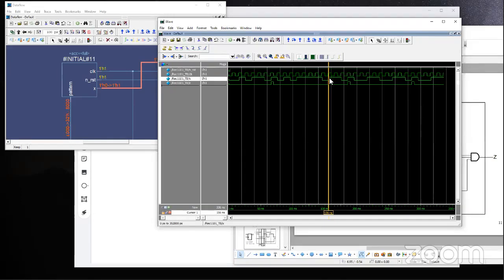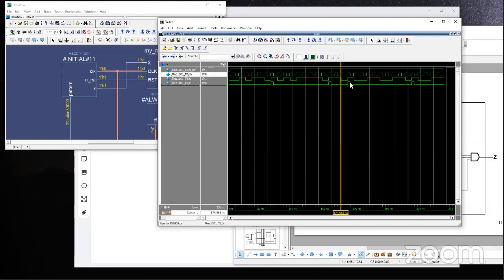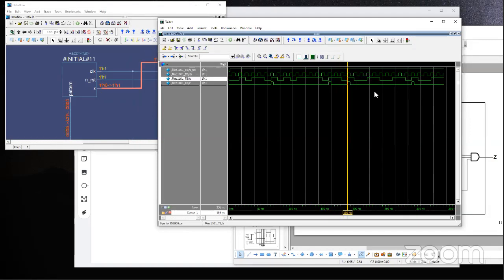And then I have this, it is going 1, 1, 0, 1. Okay, this is good. Yeah, I think this machine is working okay. It is recognizing the incoming bit pattern and saying that it sees the last 4 bits as 1101. And yeah. Question?